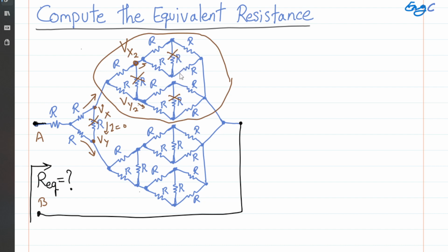With that in mind, the circuit can be simplified as R in series with R, 2R, and so on. So you have this format. You have 2R and you have 2R, which in parallel gives R. And then after that, we have R. As I said, we let go of this resistor, so we have R. And then we have 2R and 2R for the upper branch.